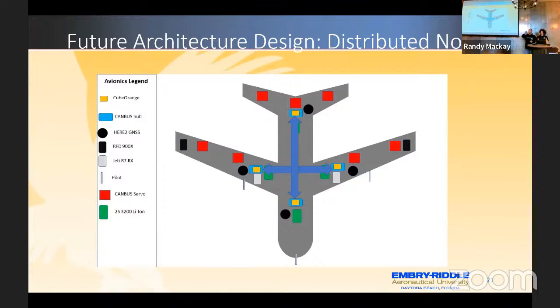This little beastie, which I've probably shown a few of you, is our little CAN bus node that we're sort of working on. It has enough power on it to run ArduPilot a few times over as well. So a concept of a more distributed autopilot system on a distributed CAN bus also can deal with issues like structural damage to the aircraft, taking out a CAN line or something like that as well.